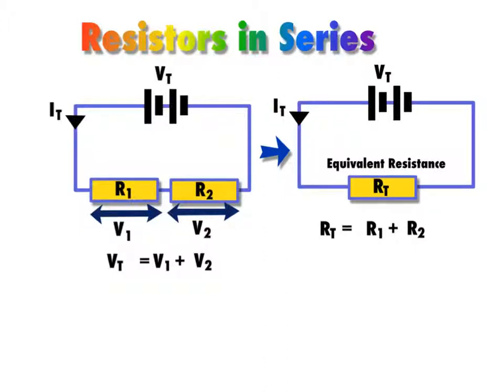And then you've got the option of coming back to these individual cases and finding what you get when you multiply that total current by that resistance to get a voltage, because you can use Ohm's law on a little bit of a circuit as well. So we could find V1 by multiplying I by R1, and we could find V2 by multiplying this I by R2. So by knowing the total resistance and the voltage being used, we can get a total current.